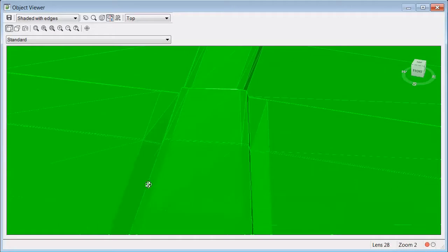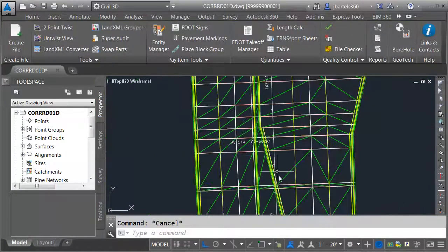So in the event our design required that -2% gutter slope, I can maintain that all the way up to the end until I get to that last assembly insertion where I've reversed the slope direction. Now that I've made this change, let's assume this is our design intent. Next, we'll add some overrides to the other end of this median. I'll close the object viewer and I'll press escape.